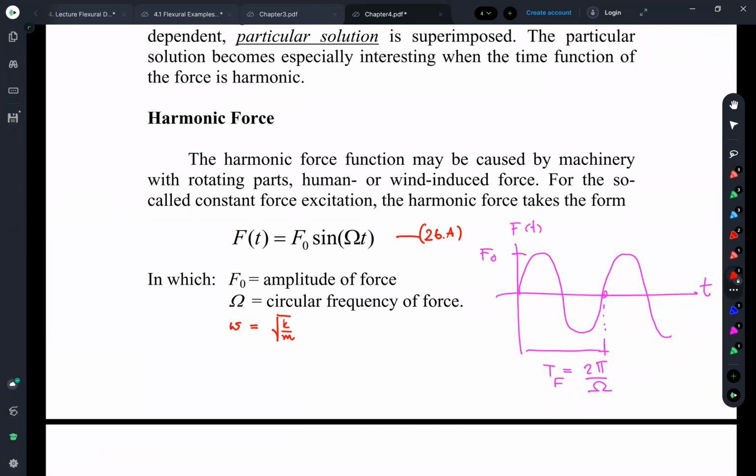So the small omega, and I often mention omega, meaning this small omega, is a property of your system, of your building. It's nothing related to the force. It's a property of our building itself. It has a natural frequency: when we move the roof of the building a little bit, maybe 10 centimeters, and release, the building goes back and forth by itself.